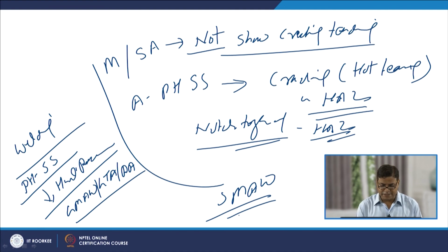Now, I will summarize this presentation. In this presentation, I have talked about the various technological issues encountered during the welding of austenitic stainless steel, like chromium carbide formation, reducing the corrosion resistance, and sigma phase formation, decreasing the notch toughness and ductility of austenitic stainless steel weld joints. I have also talked about what we can do to overcome those issues, and thereafter about the weldability of precipitation hardenable stainless steels and the various issues related to the welding of this kind of steels. Thank you for your attention.